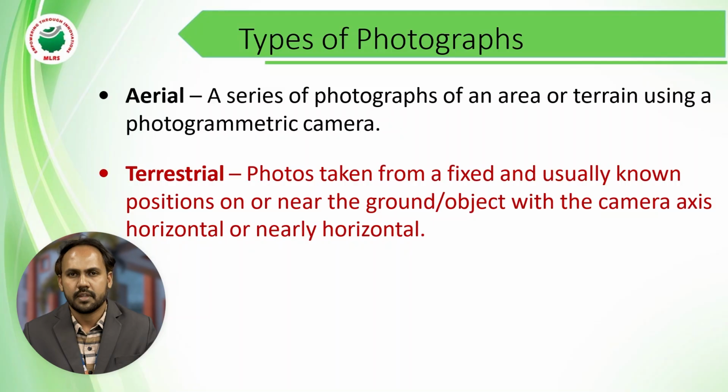With the help of vertical aerial photogrammetry, we can analyze the height of a building, how many stories a particular building has, and it can be used for mapping purposes or engineering survey purposes. Whereas terrestrial photogrammetry will be helpful for very close monitoring of structures, deflection studies or deformation studies, and identifying cracks in buildings. Horizontal or terrestrial photogrammetry is helpful for those purposes, because with vertical photogrammetry the cracks will not appear from the top view.